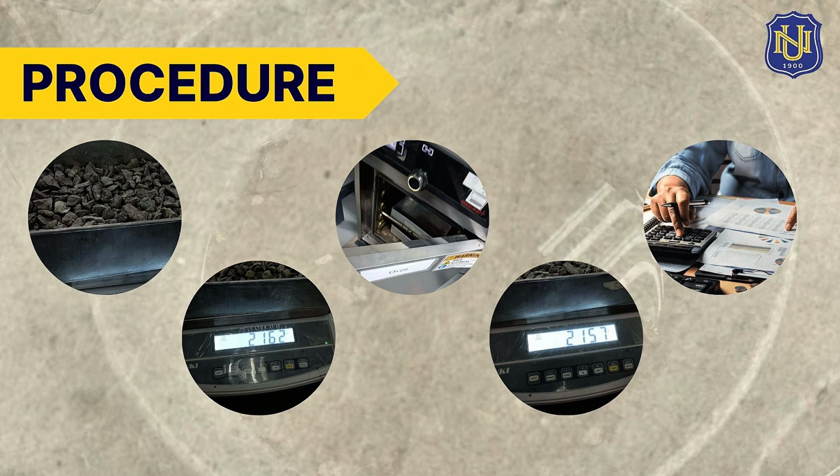Lastly, calculate the total moisture content using the formula. Total moisture content equals W1 minus W2 over W2 times 100. The surface moisture content is then calculated by subtracting the absorption value from the total moisture content. Surface moisture content equals total moisture content minus absorption. These calculations help determine the amount of excess water present in the aggregates.